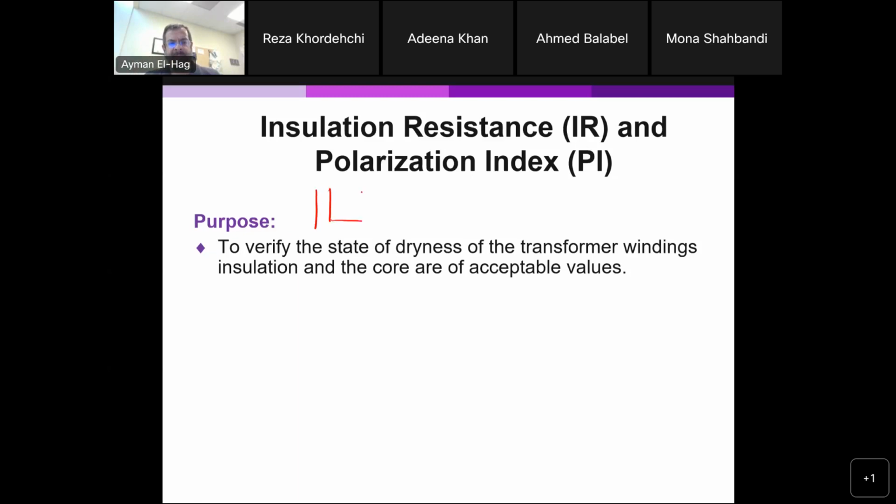For example, you have the 3-leg core of the transformer here. You assemble them. This is the core of the transformer, and then you stack them until you get the required cross-section area, and then you install on top of each leg the winding, the 3 windings, each composed of the high voltage and the low voltage winding.